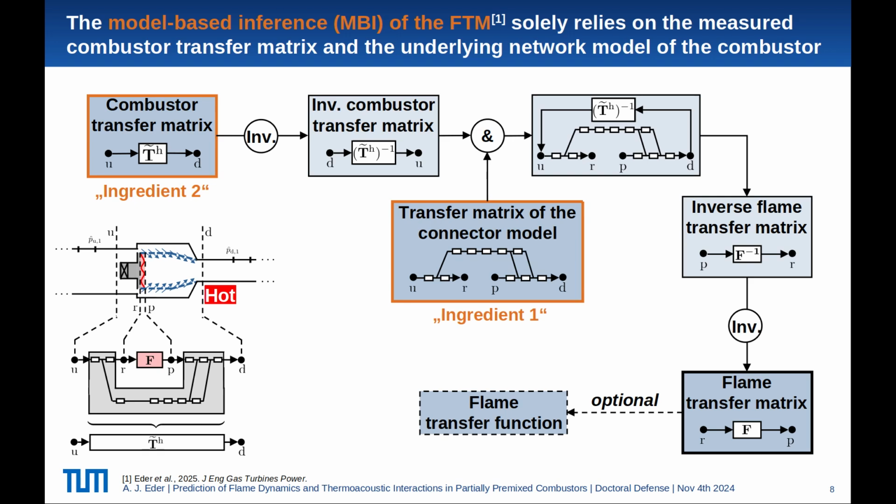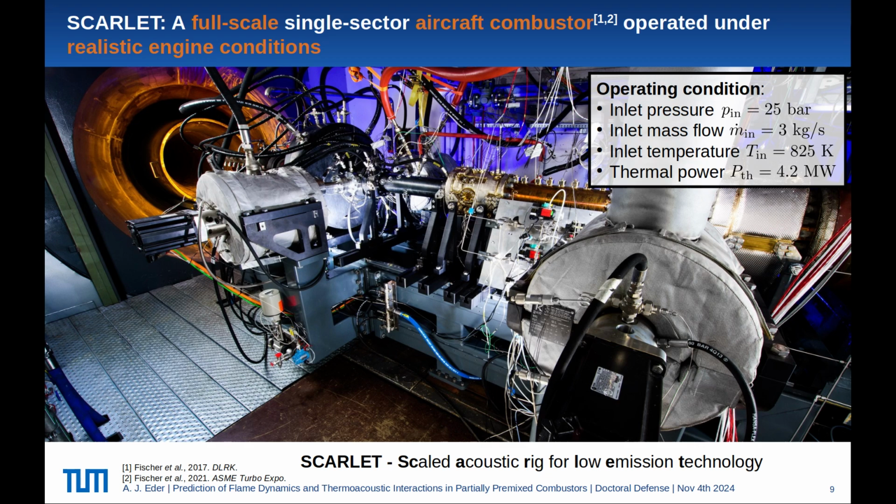And we use that methodology then, or we apply that, to real experimental data. And we use therefore the SCARLET, which is an acronym for Scaled Acoustic Rig for Low Emission Technology from Rolls-Royce. And this test rig comprises a test section, which is a full-scale single-sector aircraft combustor, and the whole rig is operated under realistic engine conditions, so high pressure, high mass flow, high preheating.